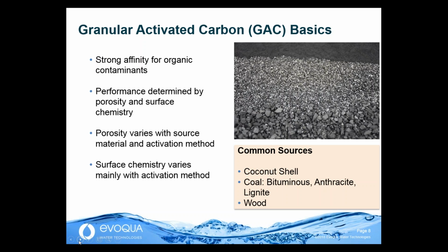Now, of course, performance of each of these different carbons is going to vary and can be tailored for certain applications as well. And that really comes down to two main parameters. That's porosity and surface chemistry. Surface chemistry for carbons used in water treatment are for the most part similar because they're all steam activated. So really the main parameter when you're looking at performance differences comes down to porosity. So it's important in water treatment.